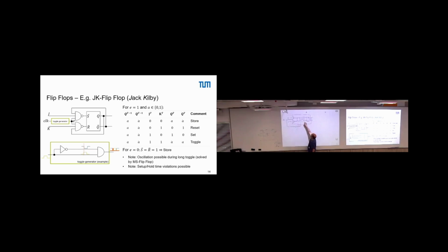In the next clock cycle, applied here, and another time inverted, and we just toggle the output. But now this toggle is not dependent on the clock, because when this here toggles, this here is inactive. When this here toggles, this here is inactive. So one propagation delay of the whole thing takes 1 clock cycle, right? So we are perfectly synchronous.